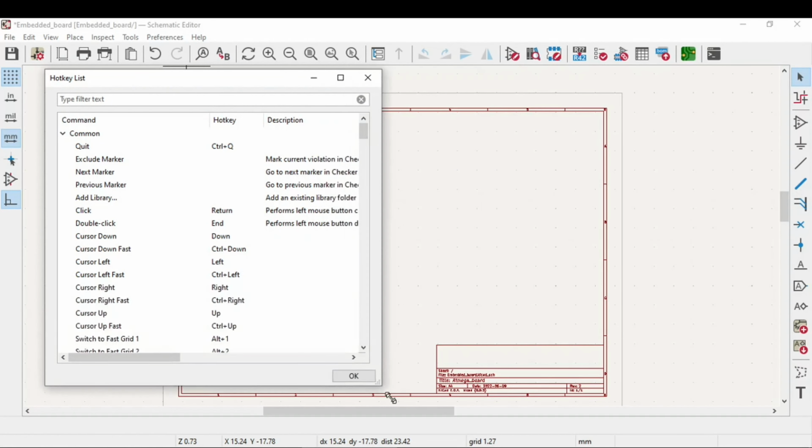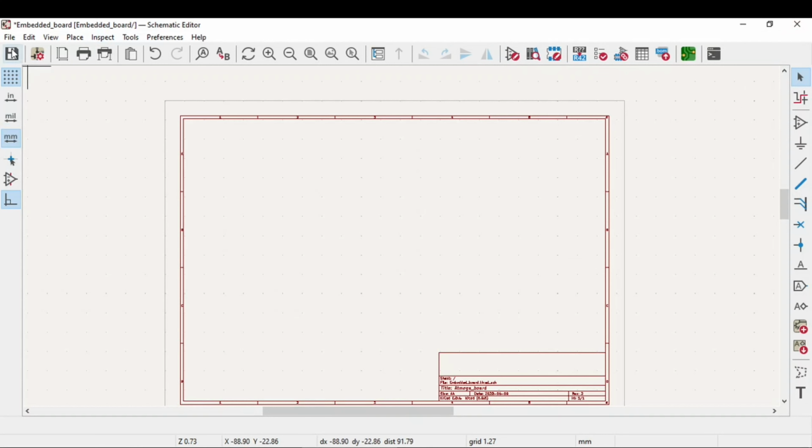If you see on this top toolbar, there are a lot of options. The first one is Save, save changes. As you go on creating a schematic, I prefer you keep saving the schematic. You can edit the schematic setup, including annotation style and electrical rules. This is the setting for page size and title block, which we just did.